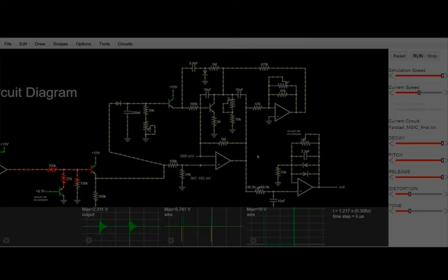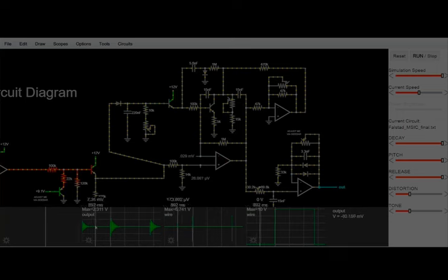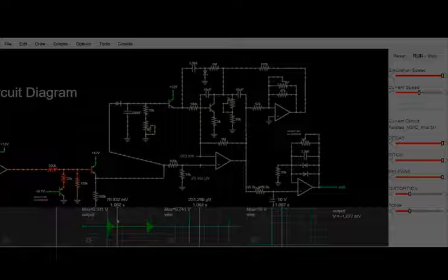Unlike a normal oscillator that continuously generates sound, this oscillator only rings briefly after receiving a trigger pulse. The circuit uses one op-amp, resistors, and capacitors arranged in a feedback network. It's the feedback network. Now, when the trigger pulse reaches the non-inverting input, the op-amp begins oscillating. The oscillation gradually loses energy and dies out naturally, creating the decaying sound of a kick drum, as you can see over here. There's a decaying sound, a decay in the waveforms.